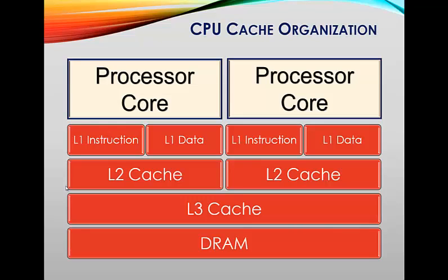When an instruction is fetched for the first time, it comes from the DRAM, then travels through several layers of cache, and I'll talk about these layers of cache in a little bit, which are hosted close to the cores of the processors. The higher you go into the hierarchy, the faster the read and write access to your cache memory will be, and also their sizes will be smaller.